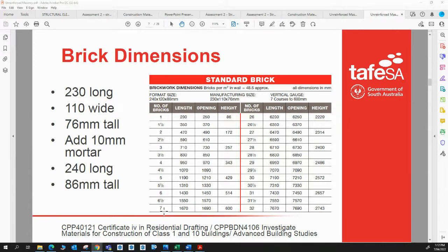And so yeah, that's a very important aspect for designers to think about when working with brickwork: you've got to be designing for those standard dimensions of brickwork. Whilst bricklayers can stretch or compress things just a little bit by making their mortar gaps slightly thicker or slightly thinner over a run, it's going to work so much better for them if they're only cutting bricks in half and doing their standard 10mm mortar gap.